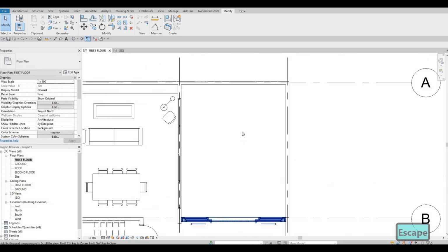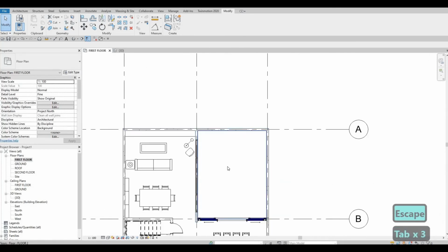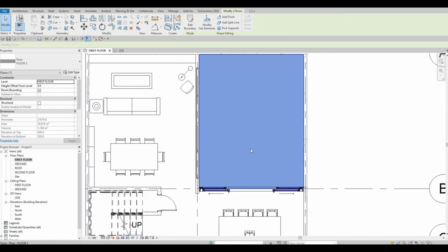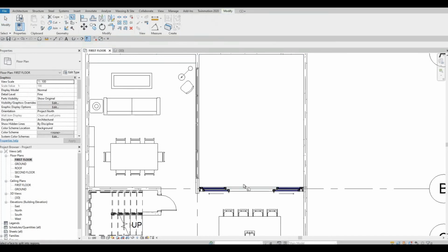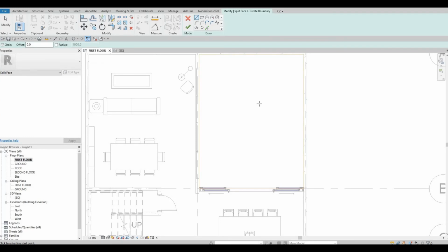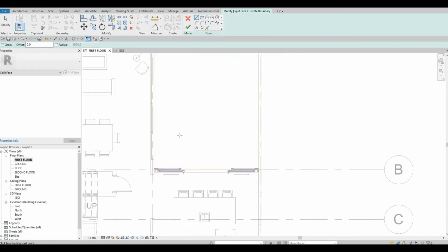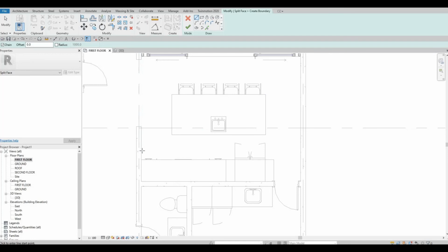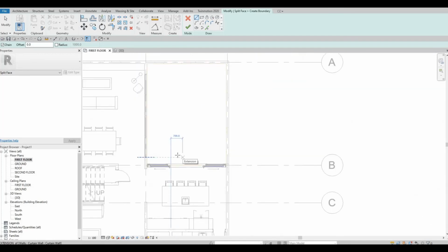We did a flooring here for the grass. So what I'm gonna do is I'm gonna make a corner here. So I'm gonna click on split face, try to select this floor. So this can go to walls as well. So you can split face wall. We can actually do it from here, but I rather have the thickness so that when we have visuals here, you can see the thickness of the tiles. It's not like flat, because this one can be flat.